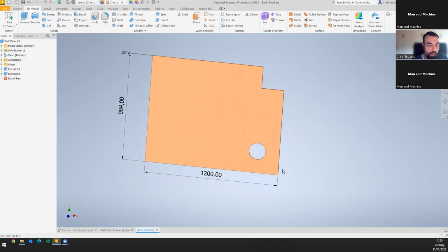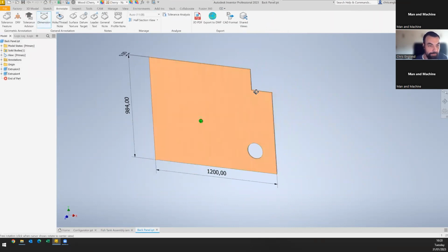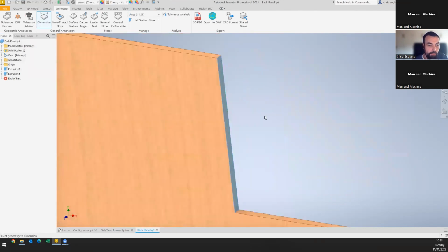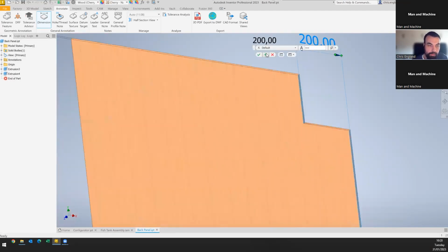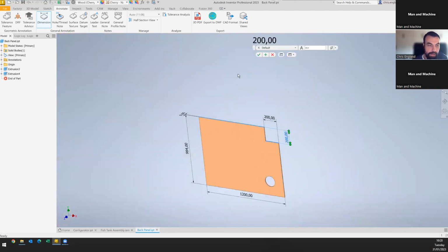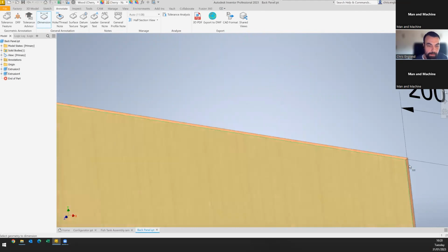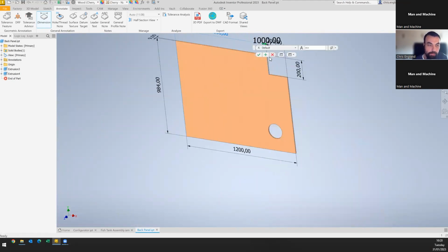Great. Now I want to ensure that when this drawing gets automatically created, that those dimensions come through. So I'll just place some quick 3D annotations. And of course, this is now optional to the designer. In the case of a once-off, this is just a bespoke cut that the client requested. I don't necessarily have to do this as 3D annotations, but I'm just going to run with it quickly to show you that the dimensions will just pull through like all the other dimensions. As long as you're placing them on the planes that you plan to create your views with, it'll work out fine. So I'll place just those.